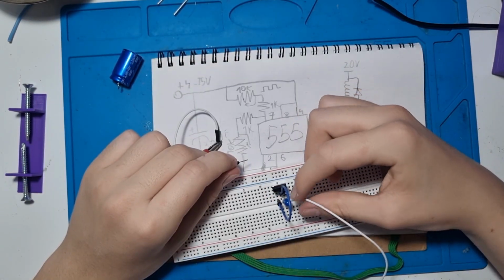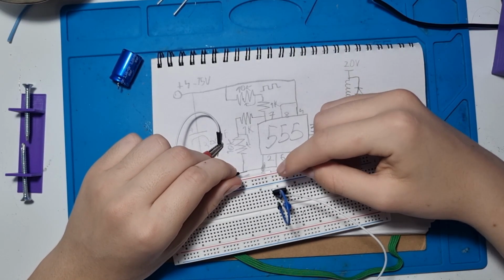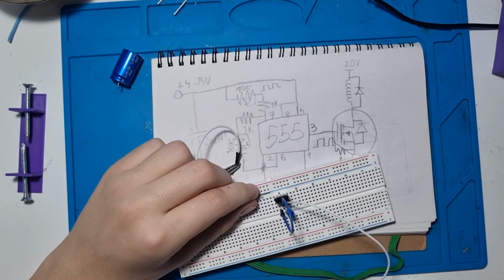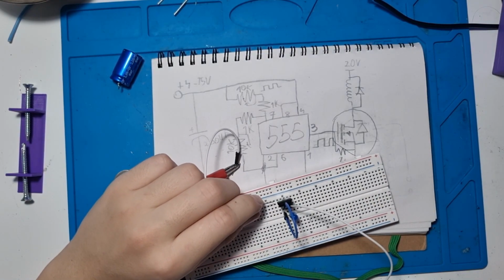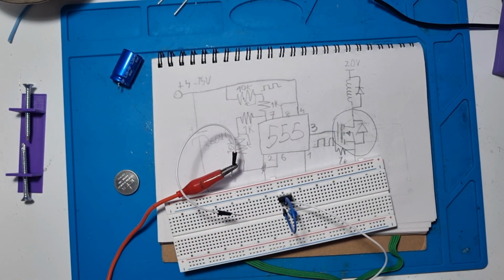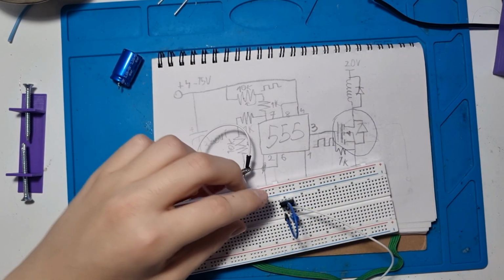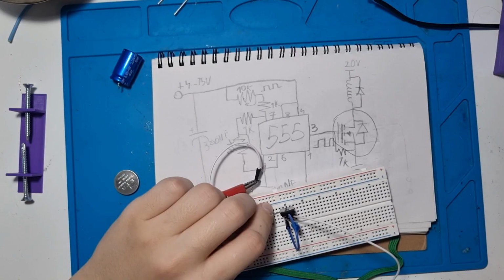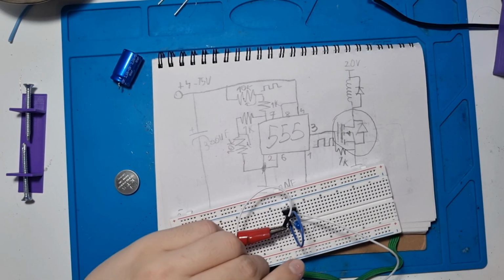You should add a resistor. I'm doing something very bad. You should add a resistor to the gate, first of all, to the gate to source, and also add a resistor after the LED, because you're basically killing the LED at 5 volts. Let's see, what if I drive it? Will it turn on at 3 volts? Still turns on. 2 volts? Doesn't turn on, because that's the turn on voltage for the MOSFET. The diode still won't turn on.